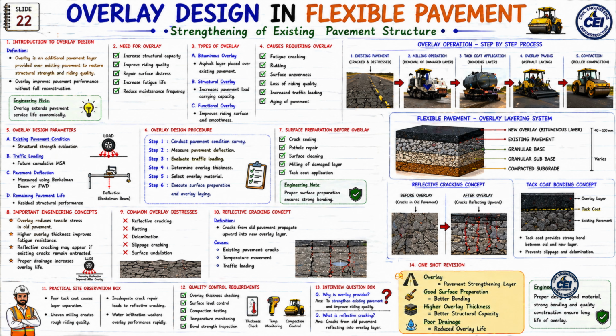Now let us look at the 10th topic. Reflective cracking concept. What is reflective cracking? Cracks in the old pavement propagate upward into the new overlay layer. Now look at its causes: existing pavement cracks, temperature movement, traffic loading, and the right side image shows this crack propagation.